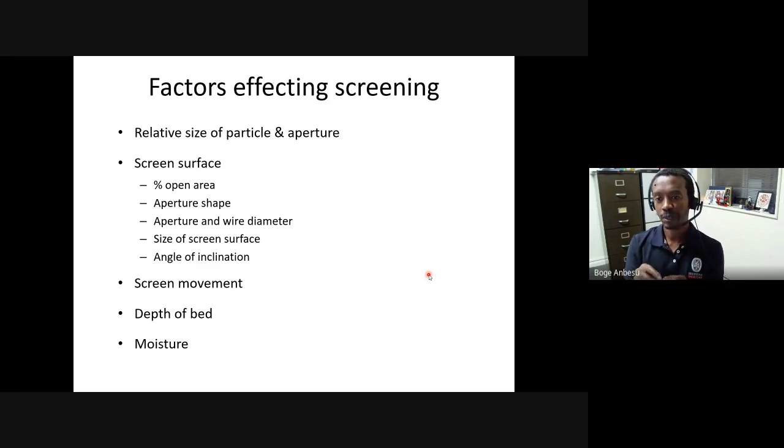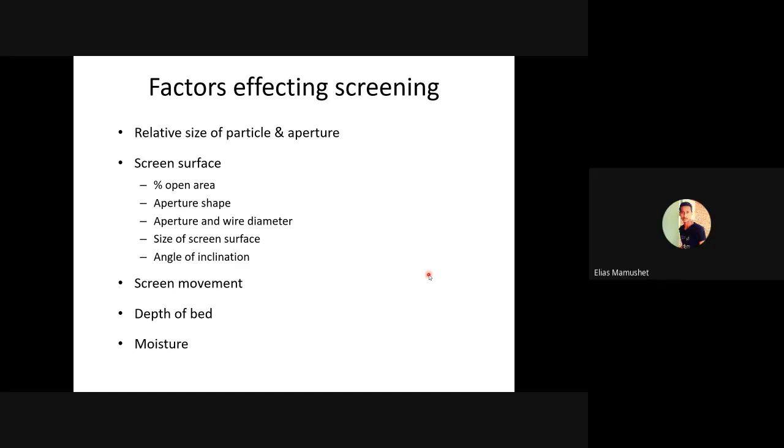If, for example, the majority of the particles are somewhere around 90 micron, 95, 105 micron, and so on, those particles are very close to the screen aperture size, which means it is very difficult for those particles to pass through the screen. So the screening performance will drop very significantly. So you need to work that out and determine exactly the proportion of particles near the aperture size.